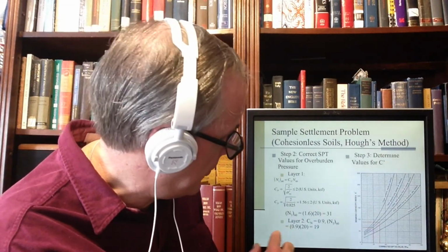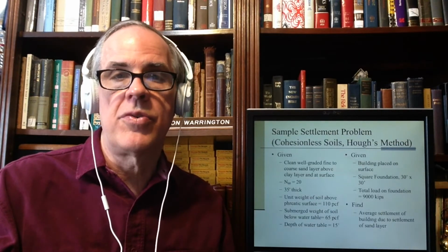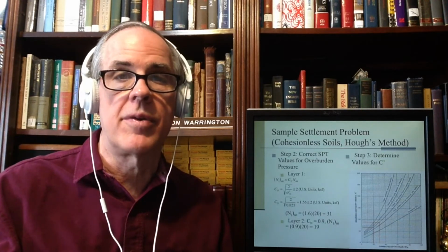And then layer 2 is different because you have an entirely different effective stress, and normally a different blow count as well. In this particular case, we're using the same blow count for both of them. That's not necessarily the case. The two layers can have different blow counts.